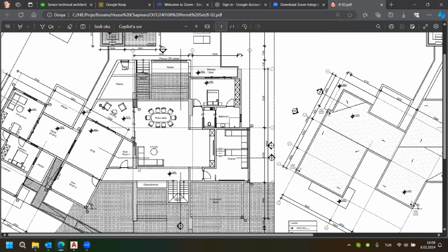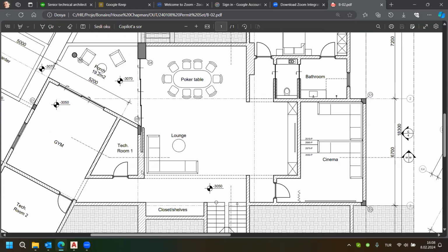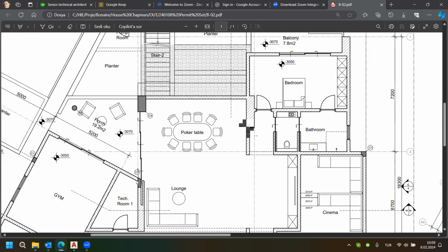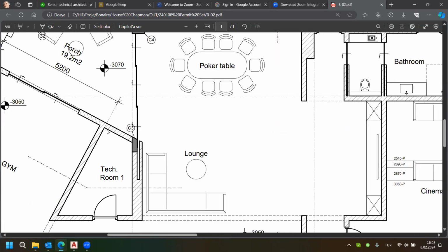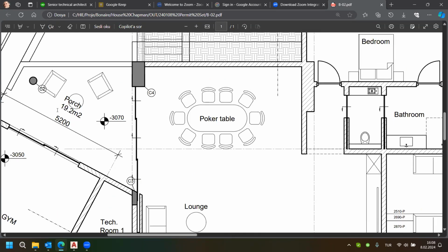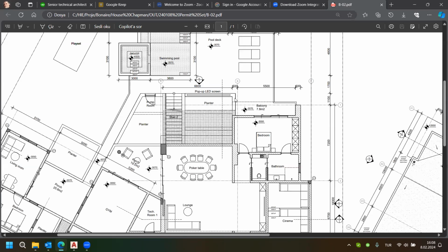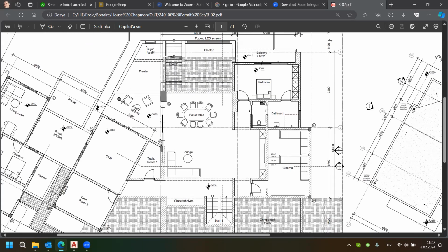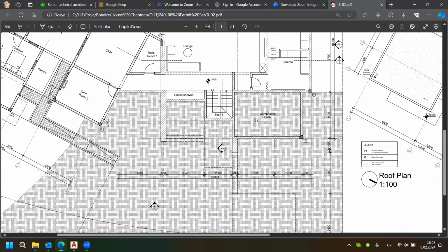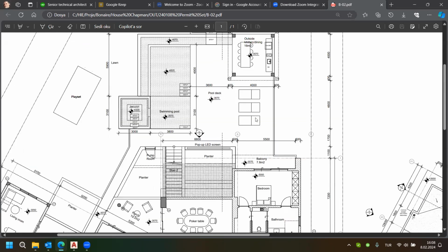Like, for instance, the hatches are a little bit gray. The wall lines, wall thicknesses, are a thicker line than dimensions or the furniture, so that they punch out. And so the contractor can see what's above and what's in the background, etc.